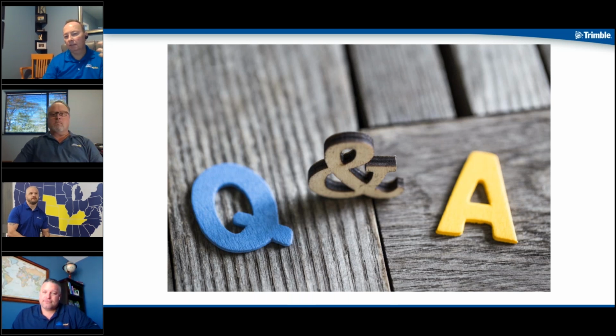If you know that Prism Constant, you can come in and use that. So when we talk about a reflector or a prism, we can put that Prism Constant in there and tailor it to your peanut prism or whatever you've got. And if you go out and mount these 360s all over the buildings or whatever, just make sure you select the proper prism in that drop down and then go to work.